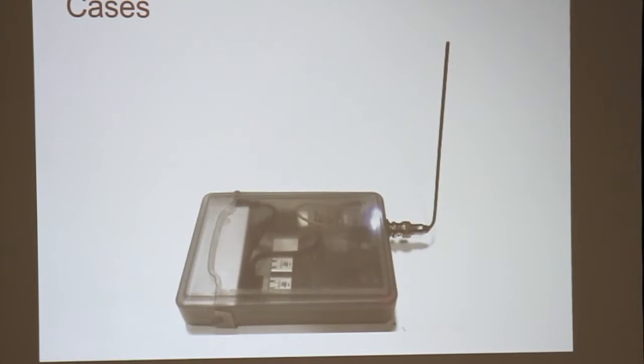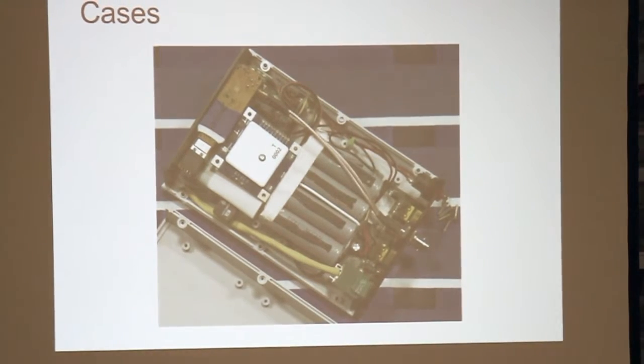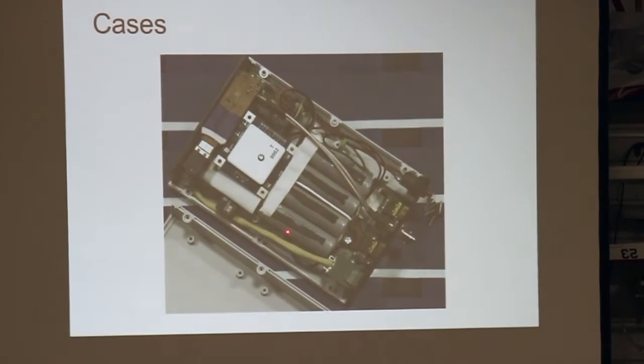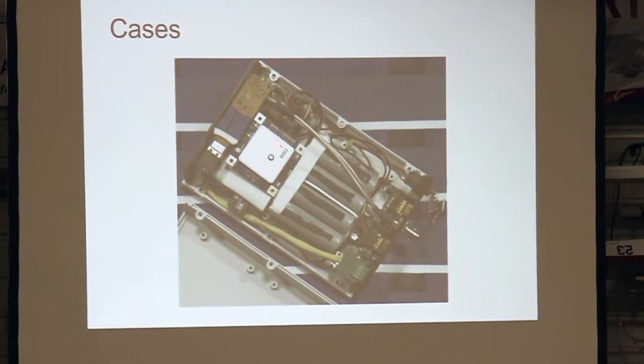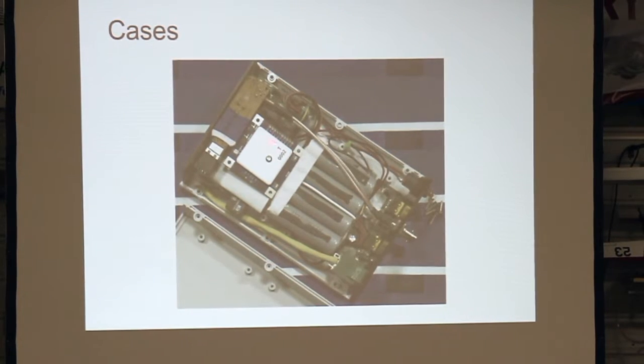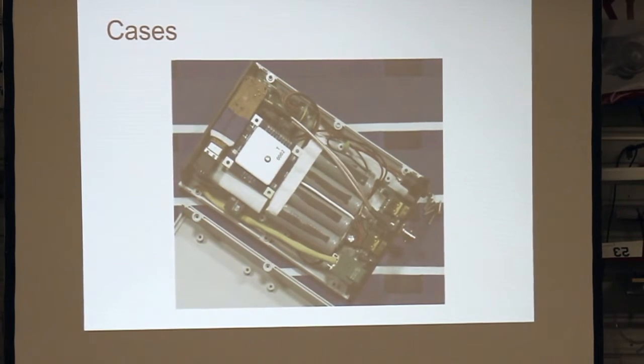More cases. This is a hard drive case. I think it was less than $2 for the pencil case. This is a modem, an old modem. It's turned into a Stratux. This is what's inside. He did a pretty nice job. He has the battery, 2 tuners. This is the RY835AI. It has AHRS and GPS. And he cabled it to a BNC cable, which he hooked up to his belly antenna. That was pretty nice. And a power button too.